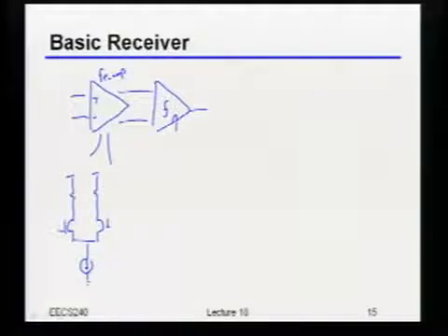So as we already talked about, the reason I say I probably want this front-end amplifier is that I want to make sure I get enough voltage swing at the input of the comparator, but I don't want to pay a lot of power for it. So as we'll see a little bit later, you could argue, well, what's the difference between what's inside this comparator and this amplifier?